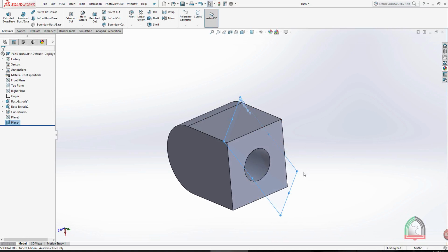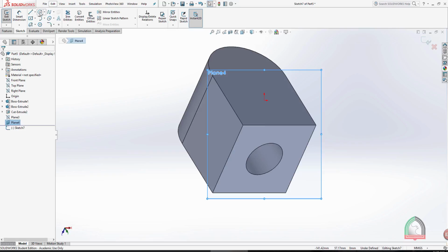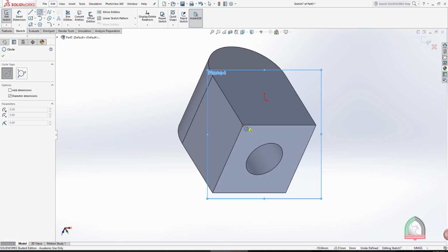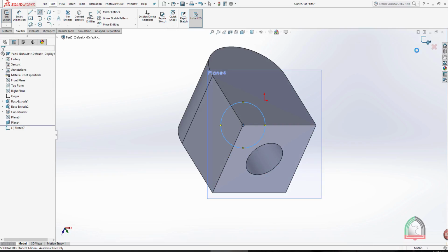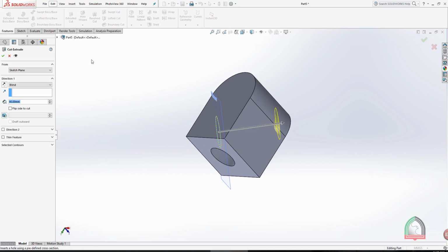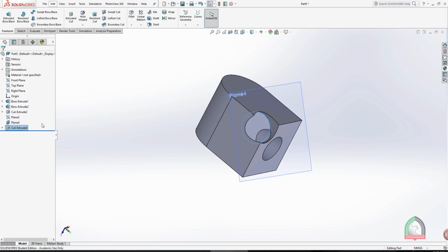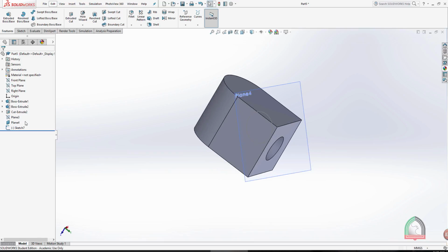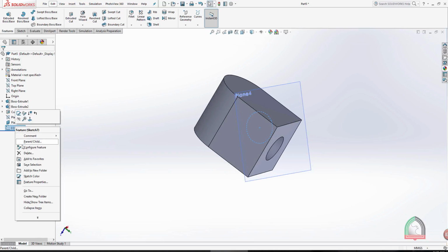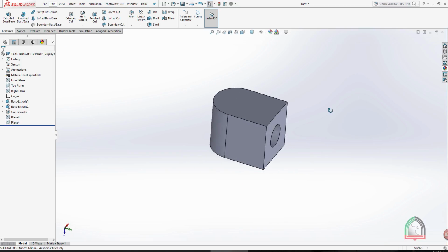I can select this plane now for drawing. And it will be like this. If I'm drawing a circle, this circle will be perpendicular to that face. Here you can see the difference. See, the circle is in the plane itself, and if I want to remove something, I can remove it along the path. So this is the application. Now I'm taking it back and I'm going with the second option. I'm deleting this plane, also hiding this plane. Now the second option